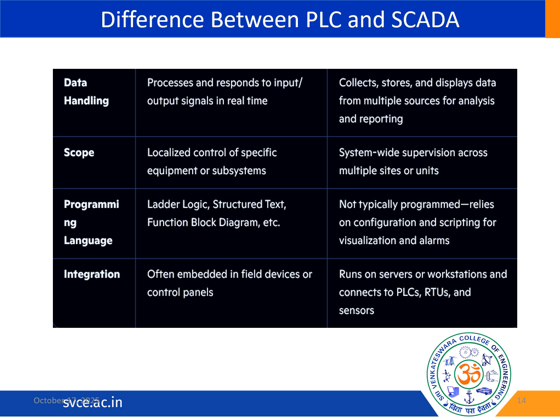Here we also use SCADA for logging information. The data that is logged and stored in the SCADA system typically arrives through communication. The PLC will continue to execute its program, reading the inputs and writing the outputs. The SCADA system is used to keep a log of the historical state of these inputs and outputs, where we can use all this information for data analysis and auditing.